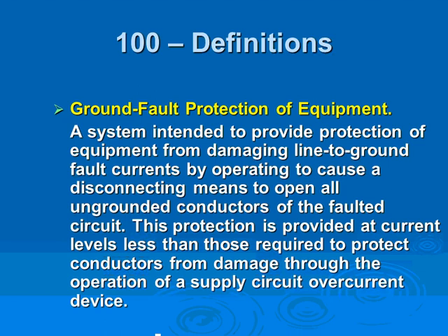When the overcurrent protection device becomes so big, like 1,000 amp, the ground fault current becomes high enough to burn your building, but low enough to sneak under the eyes of the 1,000 amp circuit breaker and not trip. After we burned a few buildings, we realized that. So now the requirement by the code says, if your system is 1,000 amp or more, ground fault protection is required. If your system is not 1,000 amp, don't think about it.